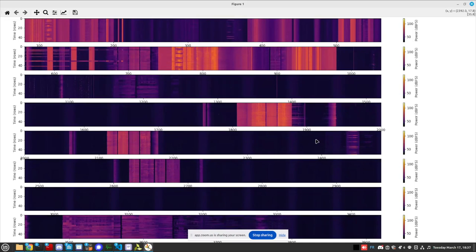which normally allows to sweep between 8 profiles. So we have 8 profiles of 60 megahertz band. So normally it's limited to 480 megahertz. And then here on the Python script, each time there is a loop, I change to another profile. And so we can have a lot of profiles like that and extend the sweep.